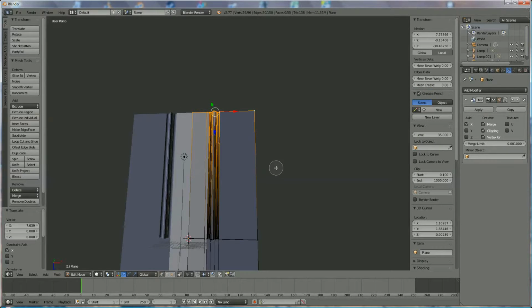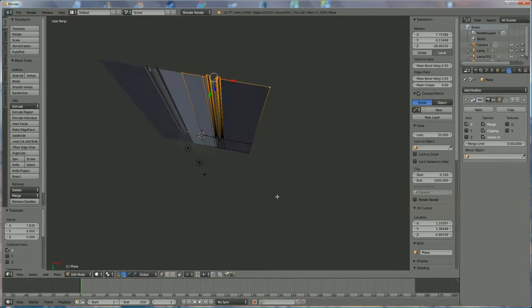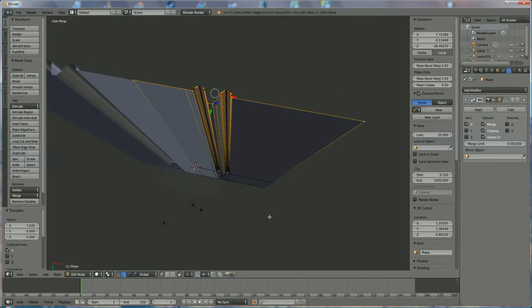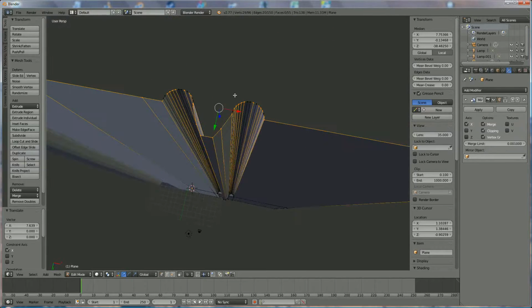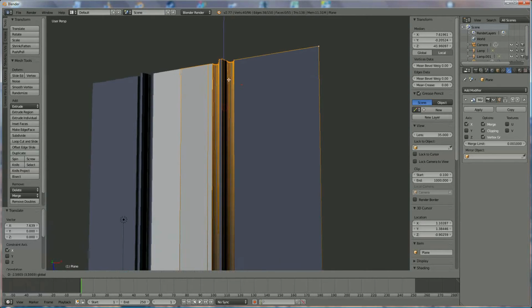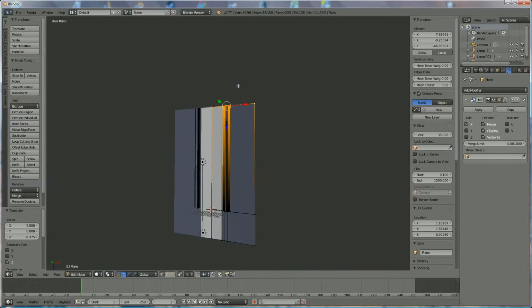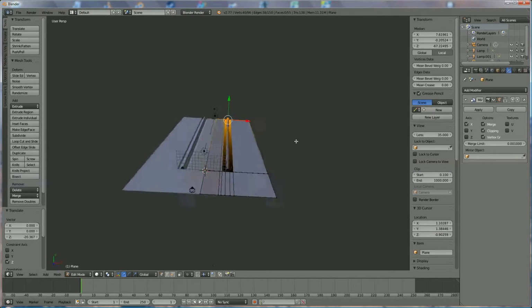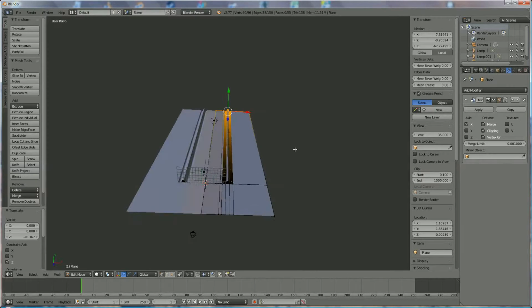Okay, I thought so. So if I have a look, you saw that I didn't select everything. Why? Because I didn't see it. So press C again, select everything like that, and if you selected everything, then you can extrude it again, or you just pick up the axis and make it as long as you want, like that. Going to, yeah, this is looking okay.